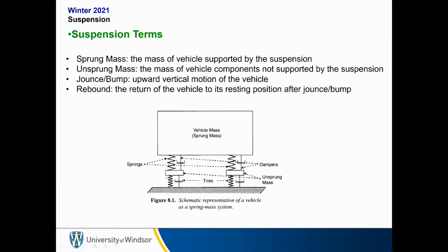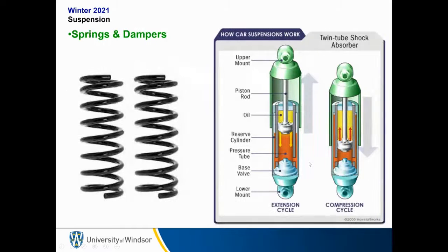The tires also act as another layer of suspension because they have some amount of spring and some amount of damping. So really the tires are part of the suspension system. But in general, we don't include anything to do with the brakes in the sprung mass, because that's not actually supported by the main suspension system.